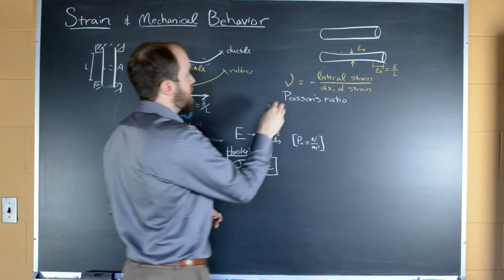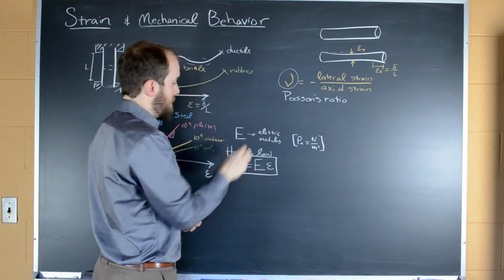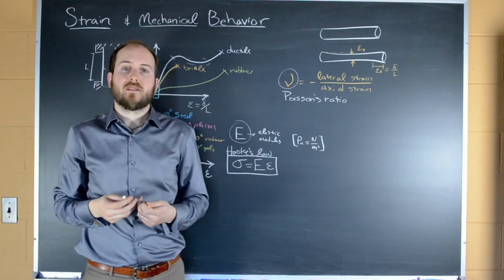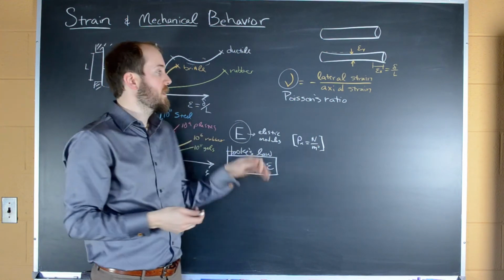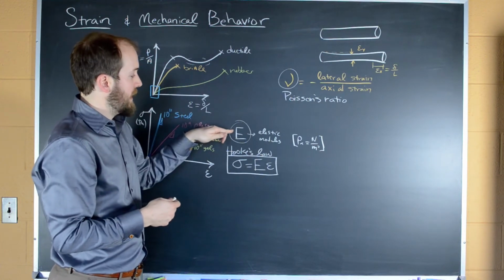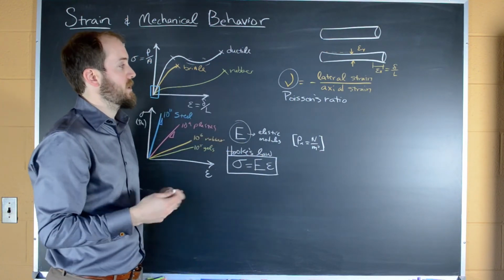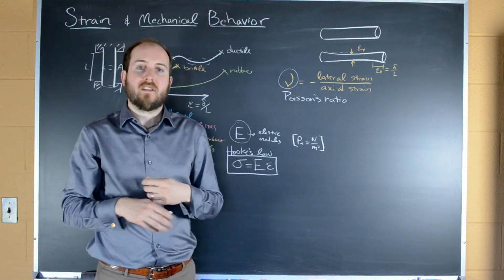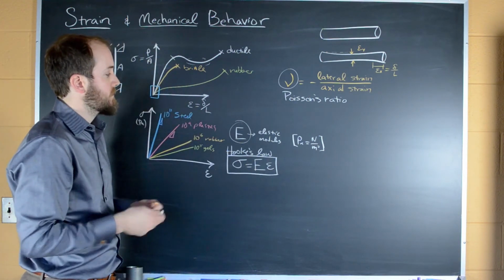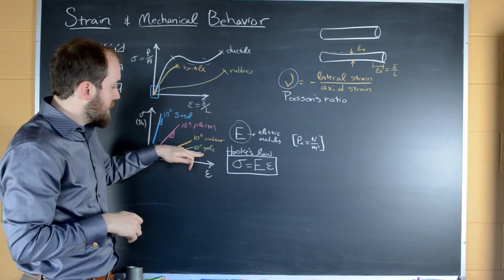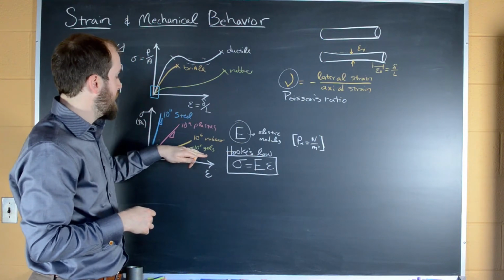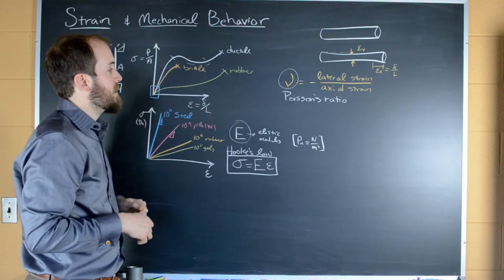And so both the things I've introduced today, nu and Young's modulus, these are material properties. So it doesn't matter about the shape of the material. A given material of wood or rubber will have a particular value of Young's elastic modulus and a particular value of Poisson's ratio. These are material properties that are valid for whatever shape or size of the material you might have. So the elastic modulus, as I've said, usually goes from about 10 to the 5, or about 100 or so kilopascals, to about 100 or so gigapascals.